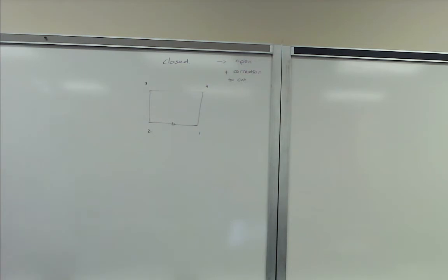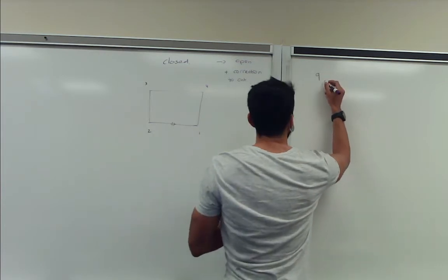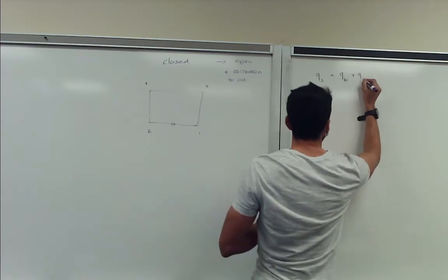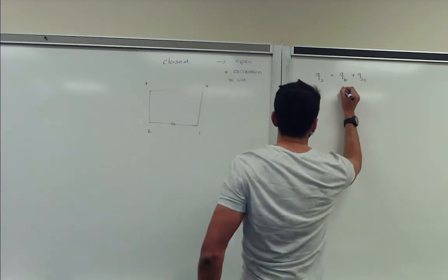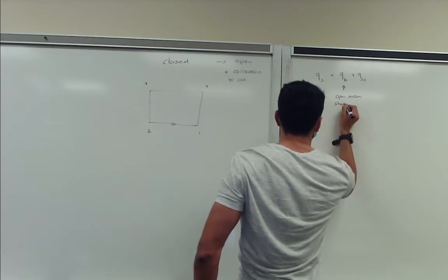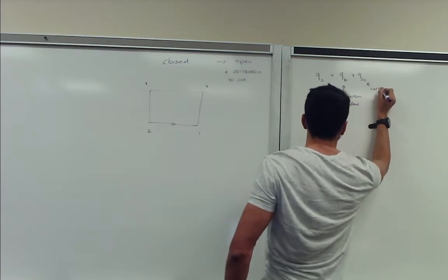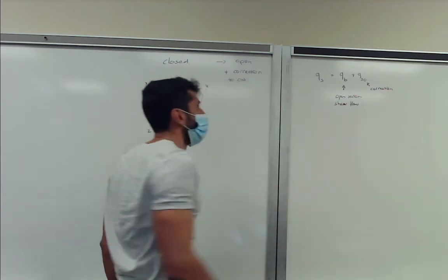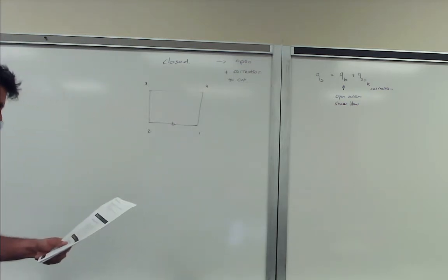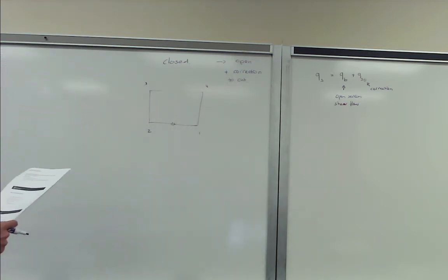To put it a bit more correctly, if we have a shear flow, q_s is our q_b plus q_s0. So q_b is your open section shear flow, and q_s0 is your correction. The subscript b is often used for basic. So the question becomes now, okay, how do I calculate this?